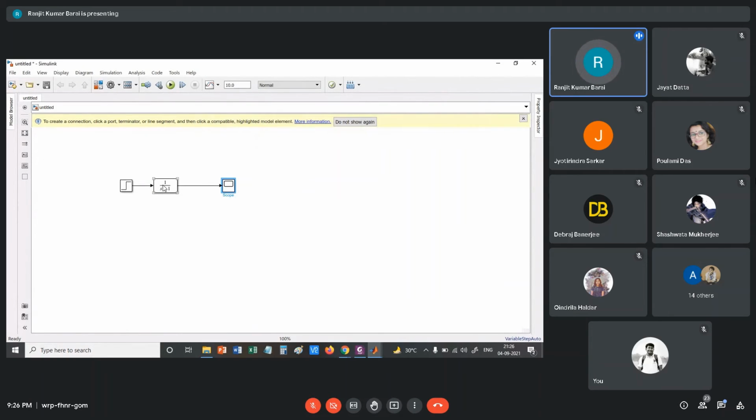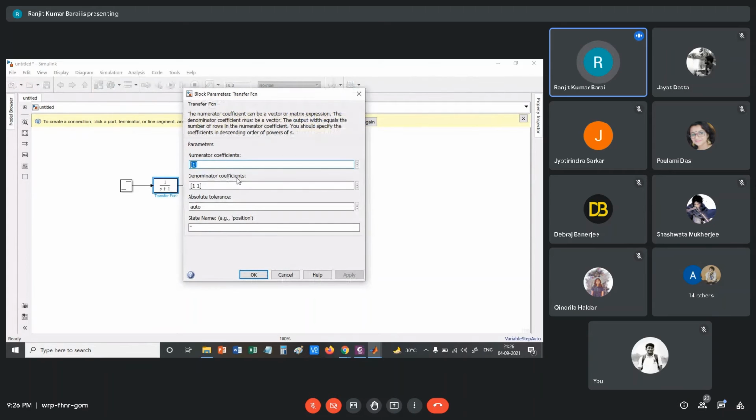Okay, I want to change this transfer function. So how to specify the transfer function? Just coefficients. A transfer function is a ratio of two polynomials of s. So here is the constant 1, shown in the bracket. Suppose I want to make it a second order. So outside at the top it is say 5.